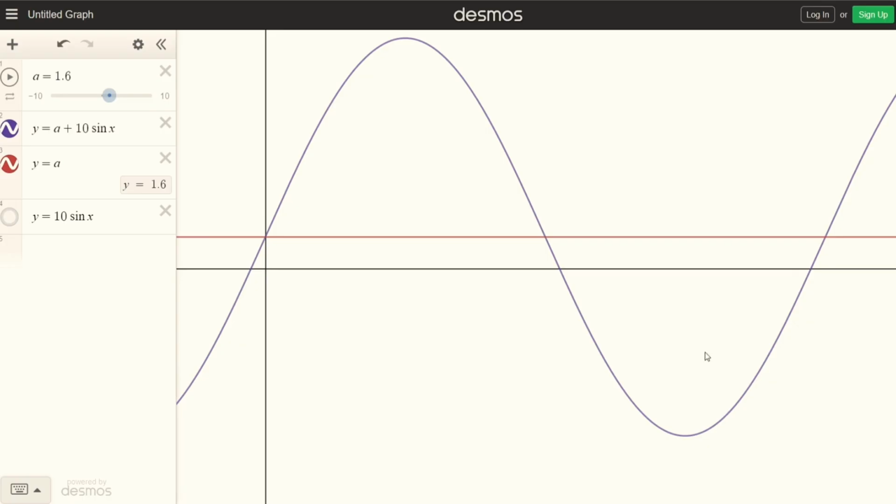Now, just a word of caution for our understanding here. The subsequent lower waveform down at the bottom here does not indicate that there's less current in the neutral than there is in the line. If this was true, then the device would trip. When the AC waveform drops below zero into the negative range, it indicates that the current has changed direction. So now when the current is going one way around the circuit, it is slightly higher than when it reverses and goes the other way.